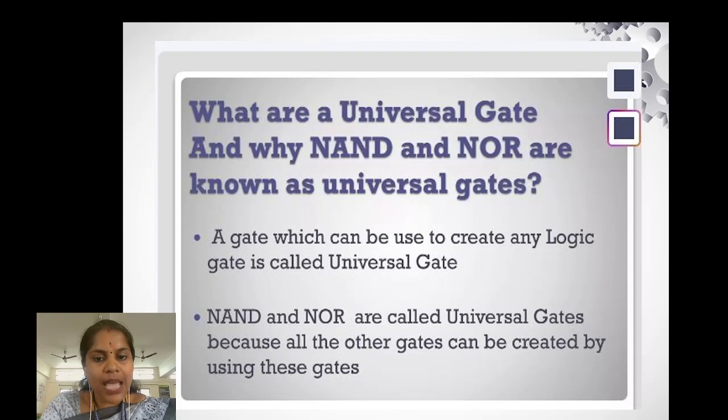By connecting the NAND gate in different ways, we can generate NOT gate, AND gate, and OR gate. Similarly, using only NOR gates, we can also generate the three basic gates. This property reduces the hardware complexity because manufacturers may only need one type of gate for building a large number of digital systems.